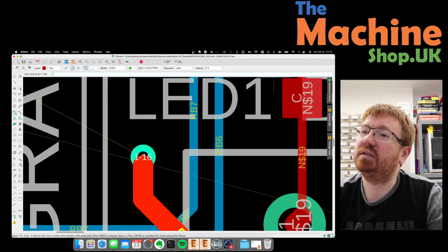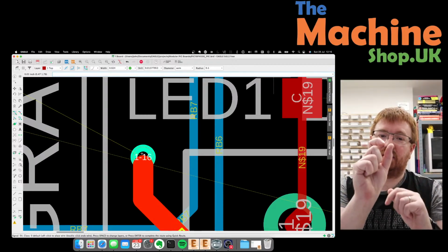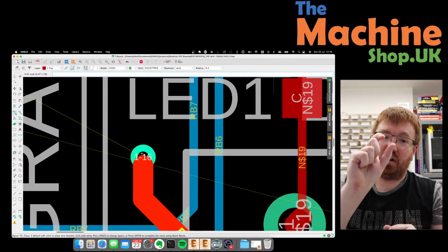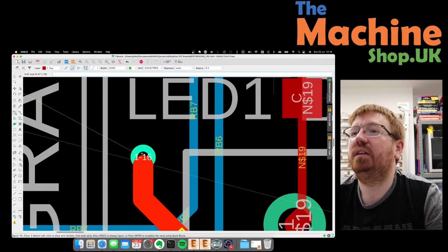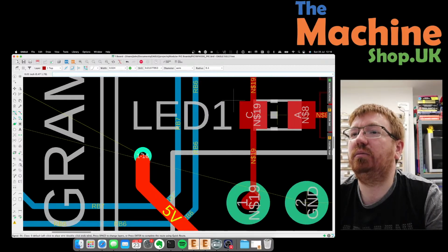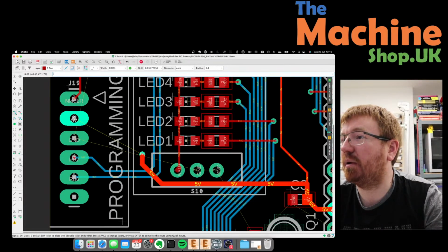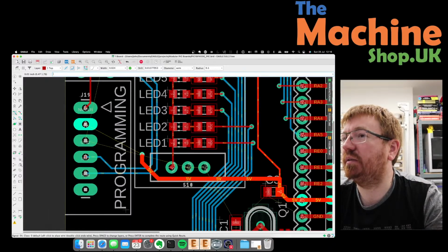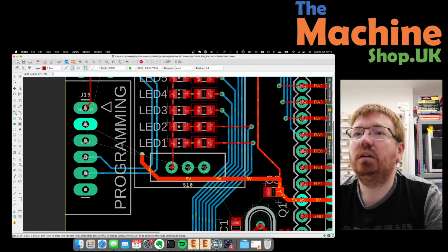Mind you, the problem is the thickness, because it's got to carry power through there. It's not so much the size of the pad, but the thickness of the wire wall is not ideal. It would be good if that was actually like a pin on something, because then the pin can carry the actual current.